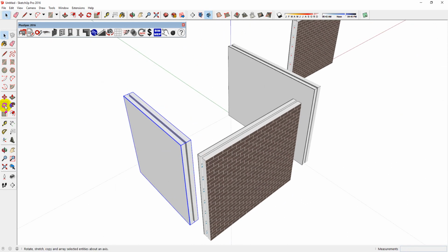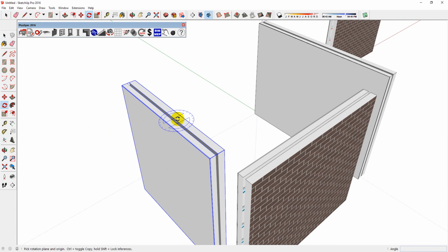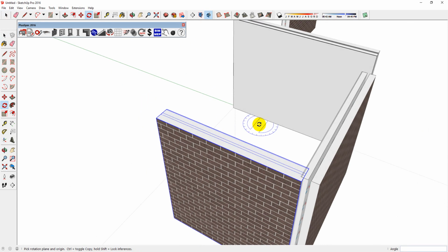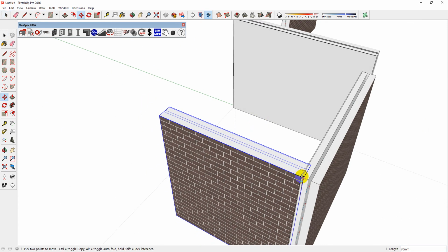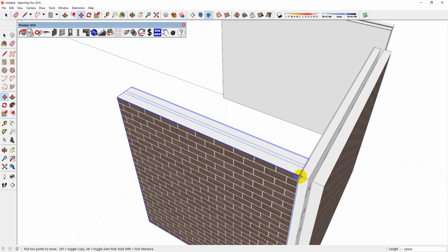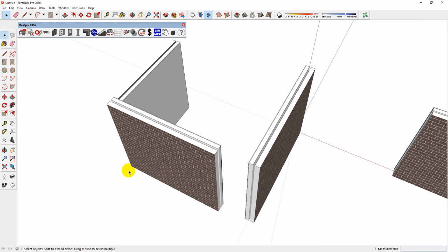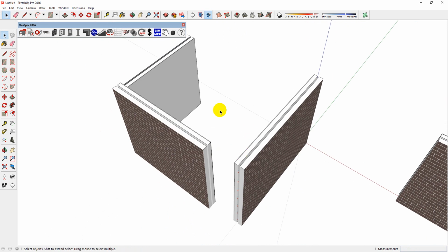Use the SketchUp Rotate tool, select a point on the blue axes, select a reference point. I like to choose the red or the green, and then spin it. You can then move it to a line. The walls that you want to join don't have to touch. However, you need to ensure that they both line up, or approximately line up. More importantly, you need to ensure that they are the same height.